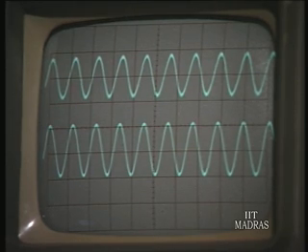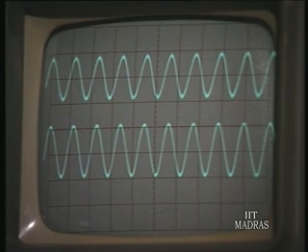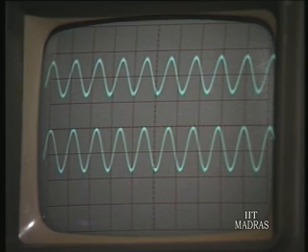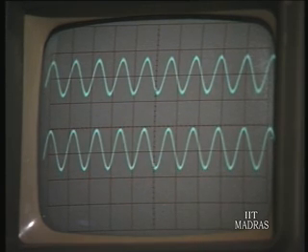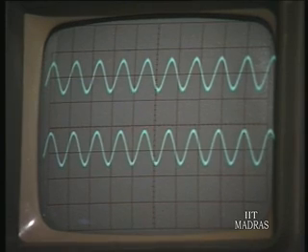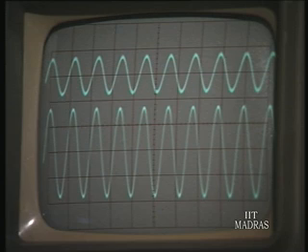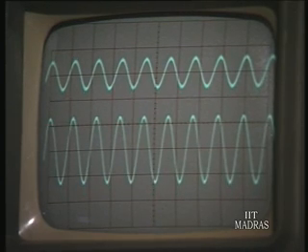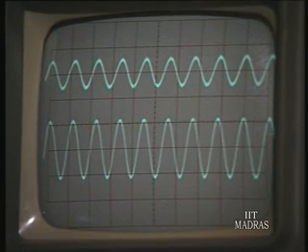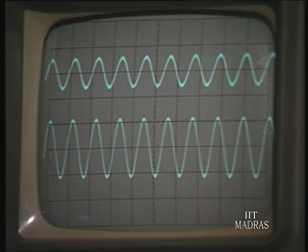That means, input is now how much? 10 volts peak to peak, right. Input is 10 volts peak to peak and output is still remaining at 0.1 volt peak. Again now reduce, go to the other scale. So she is still reducing the input, output has remained constant. Now see, slowly reduce, so that the control loop has some chance to adjust itself.